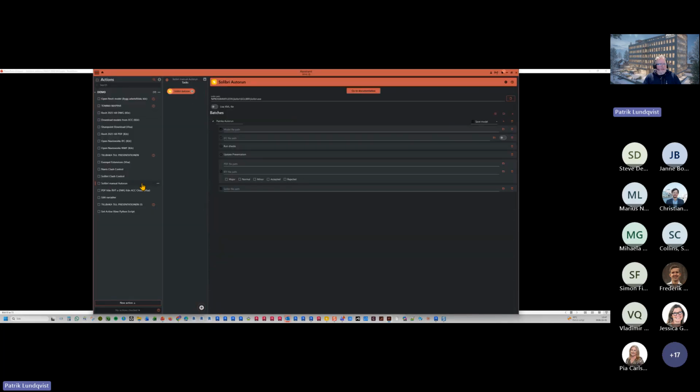So I have one set up for you here. If I turn this XML file, I choose that I want to do a Solibri AutoRun. I run it from Assistant, and then I can just go here and say, what would I like to do? I would like to open some models. I'd like to update the IFC files in these models, maybe update the presentations and write some report. And I just choose and say, where are they going to end up? And then I let Assistant do the work for me.